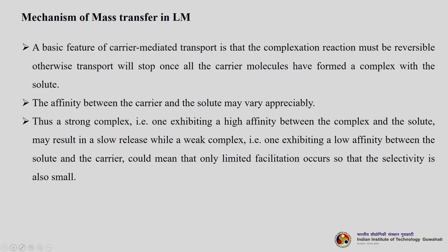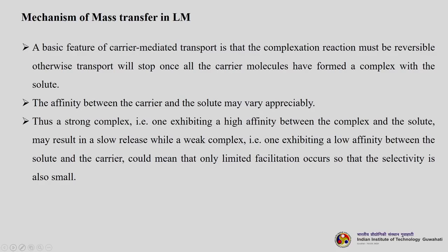The basic feature of carrier mediated transport is that the complexation reaction must be reversible, otherwise transport will stop once all the carrier molecules have formed a complex with the solute. Do you get it? If there is no carrier molecule free to bind with the solute, then there will be no more separation, it will reach some sort of equilibrium. The affinity between the carrier and the solute may vary appreciably. Thus, a strong complex, one exhibiting a high affinity between the carrier and the solute, may result in a slow release, while a weak complex, one exhibiting a low affinity, could mean that only limited facilitation occurs, so that the selectivity is also very small.